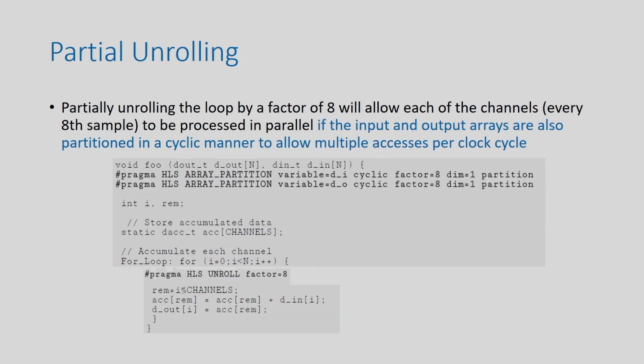So, I am going to put an unroll factor equal to 8 into this code. If we just do that, the tool will automatically rewrite this code, so basically you can understand that there will be 8 copies of this code, and I plus 1, I plus 2, I plus 3, I plus 4 to I plus 7 will be used here. I am not writing that, but I hope you understand the corresponding loop body.